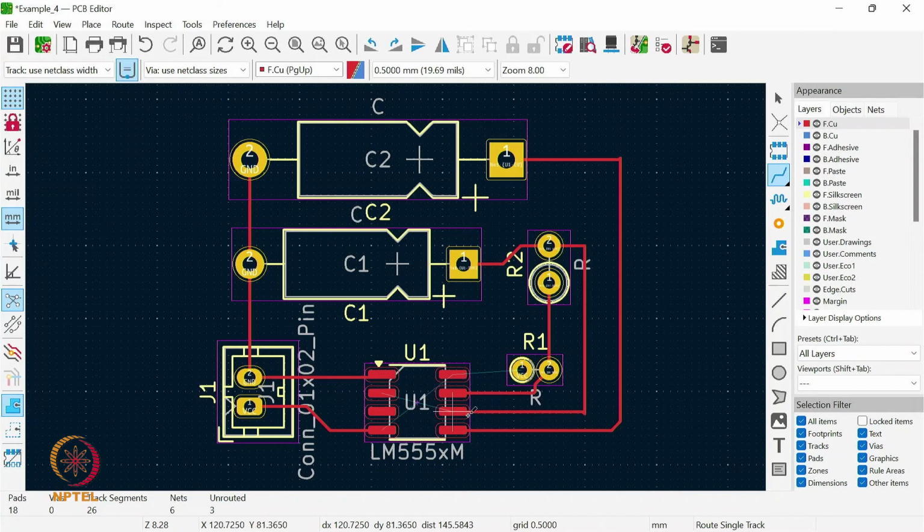Now there are two rat nests. Now we have a tricky situation. One wire we need to route from here to here, and one wire we need to route from here to here, and if we see, both the wires are crossing each other. So we cannot have two traces running on top of each other, otherwise there is a short circuit and our PCB will not work.